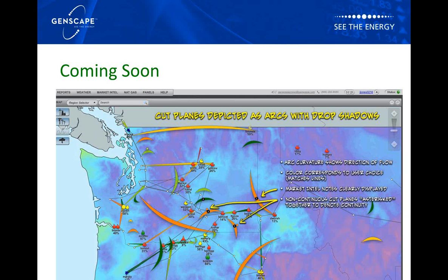And then we also do analysis on all the real-time binding constraints and look at the historical frequency, the number of hours that something is binding, what the contingent elements are, and what the shadow prices have been, and use that as a way to prioritize what we're going to put monitors on. We deploy between 10 and 30 a month, so the network's growing pretty consistently over time.